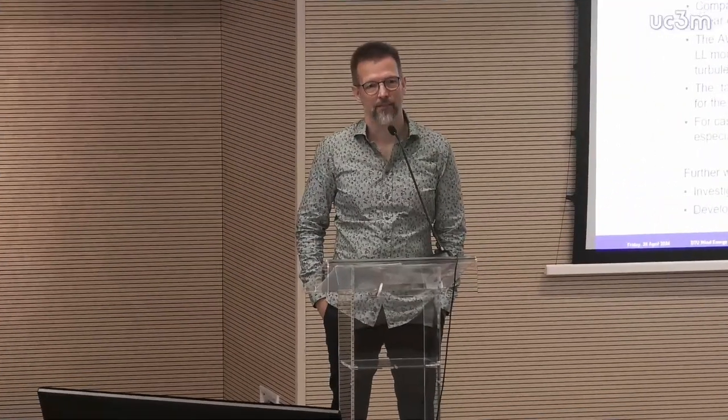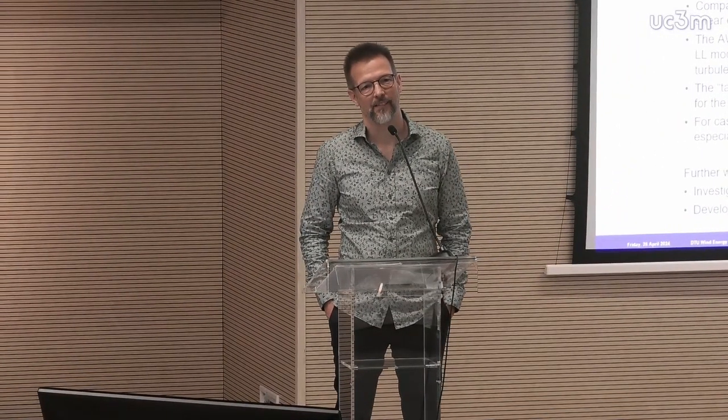And then you shed the vorticity from the actuator line method as a force F that you put in your CFD solver, and then the vorticity of that F will be shed in the wake, and it can also absorb the turbulence that you get at the inflow. So actuator line methods at some point become much easier to implement and use with turbulence than these lifting line methods, I think. Yeah, you have the problem of these trailing vortices. What do you do with them, right?